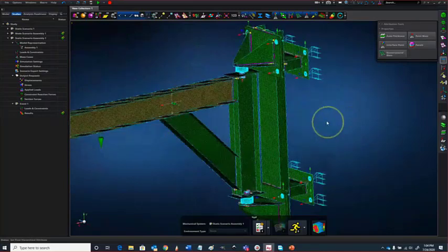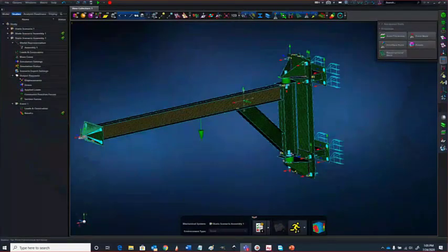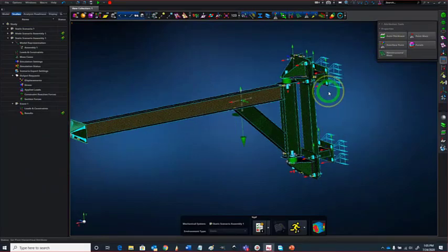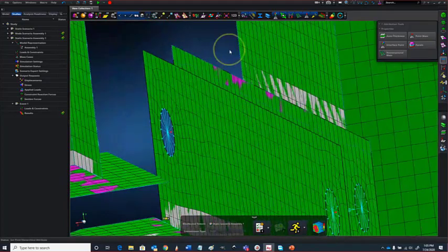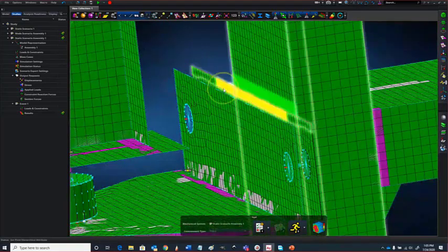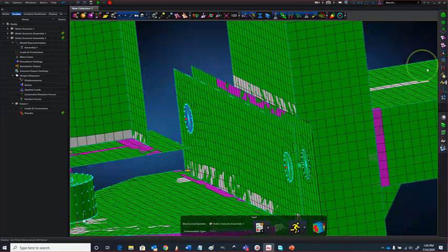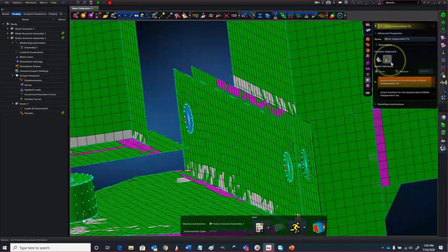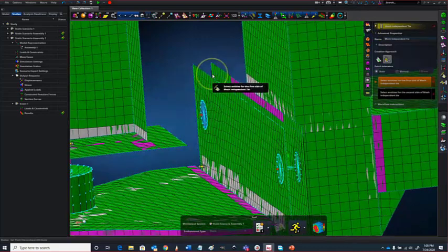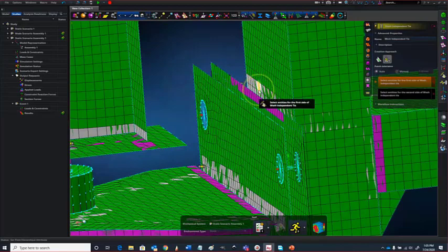Are there any other questions? Sorry, Paul. One more. Yes. When you glued the portion of elements to the plate behind it for the weld, is it okay also to maybe just glue the edge nodes? The nodes on the edge to the plate behind it. I didn't check if that is an option, to be honest. No, it's not an option. You can only select elements. Thank you. So it's like a face-to-face kind of contact.